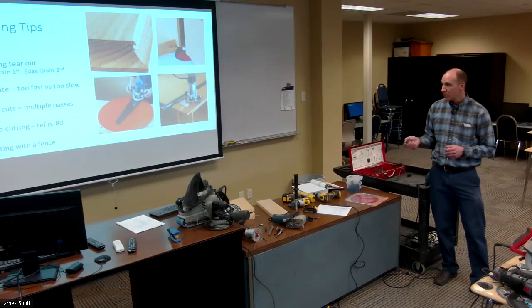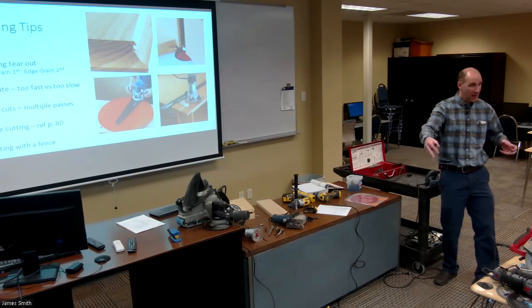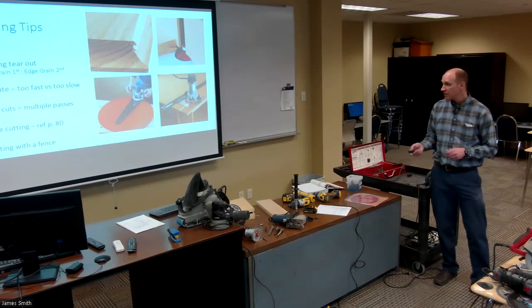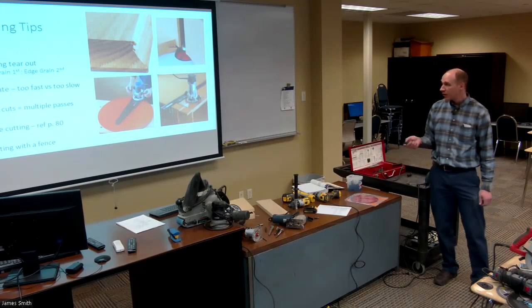If you're doing circles, you can use circle cutting jigs. Okay, those are really helpful. I've made those just using a piece of aluminum bar or flat stock. You can make those out of wood too. A little piece of 1/4-inch plywood, you could drill a couple holes, screw it up to the base, and you're ready to rock and roll.